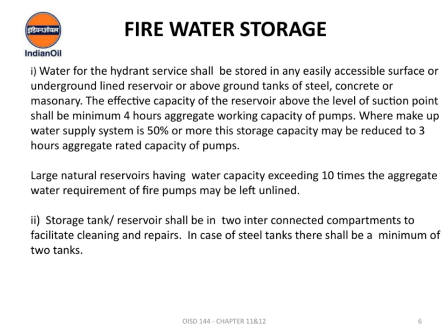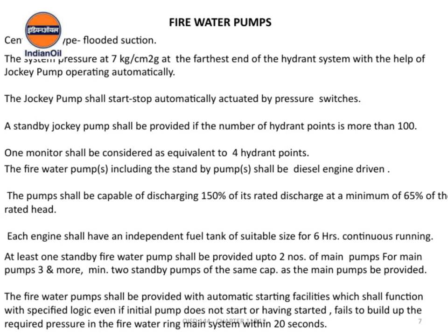Let's take a closer look at the fire water pump requirements as per OISD 144, Chapters 11 and 12. First, at least 1 standby fire water pump must be provided, and if there are up to 2 main pumps, a single standby pump is sufficient. However, for 3 or more main pumps, you need to have at least 2 standby pumps of the same capacity as the main pumps. An important feature is that these fire water pumps must have automatic starting facilities.